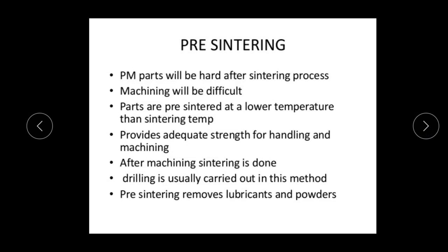Now let us discuss the pre-sintering concept. The PM parts will be hard after the sintering process, so machining will be difficult for such kinds of PM parts. Due to that reason, the parts are pre-sintered at a lower temperature than the sintering temperature, which provides adequate strength for handling and machining the PM parts. After machining, sintering is also done, and drilling is usually carried out in this method. The pre-sintering removes the lubricants and powders.